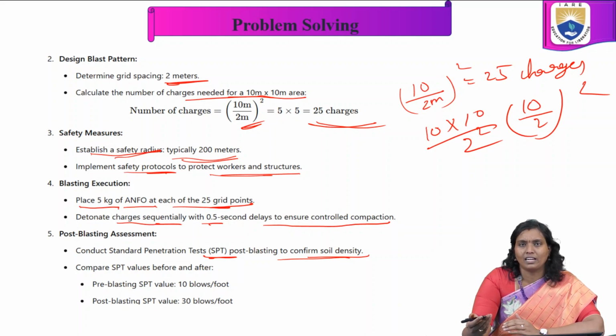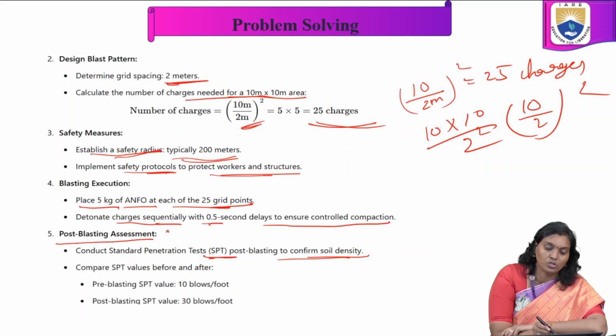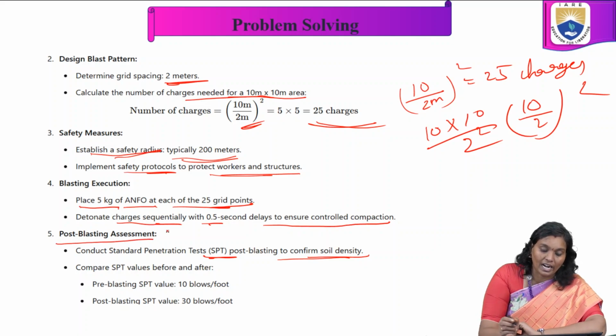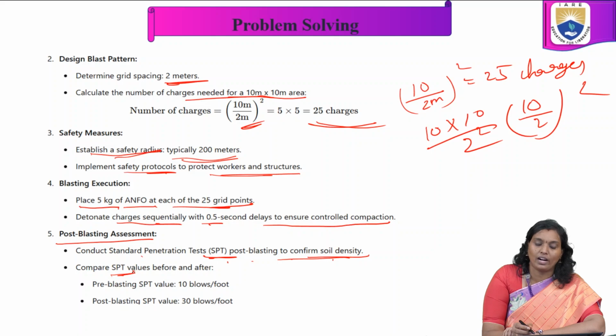Only then will we understand whether we will reach our goal, whether we will reach our expected outcome or not. It depends upon the post-blasting assessment. So conduct a standard penetration test post-blasting to confirm soil density, and compare SPT values before and after.